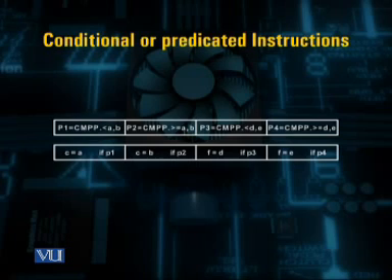And these 4 operations are: the value of C is to be replaced by A if P1 is equal to 1, whereas C is to be replaced by B if P2 contains a value equal to 0, and similarly F is to be replaced by D or E depending upon the contents of the predicate registers P4 and P3.